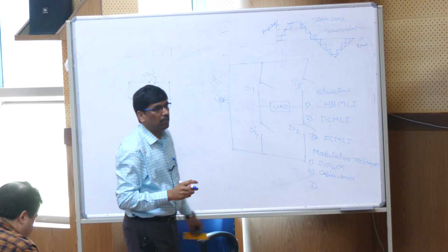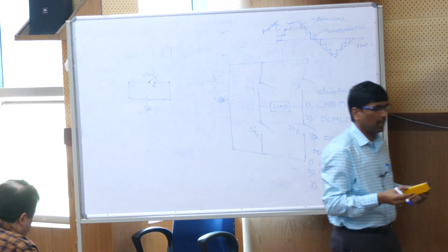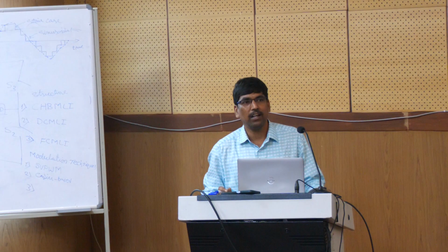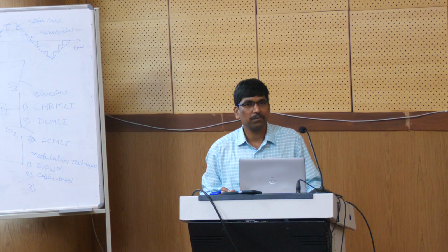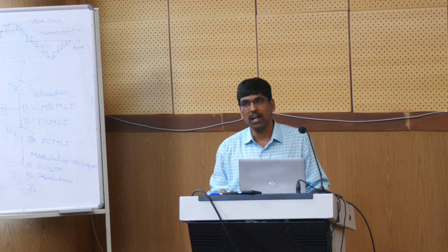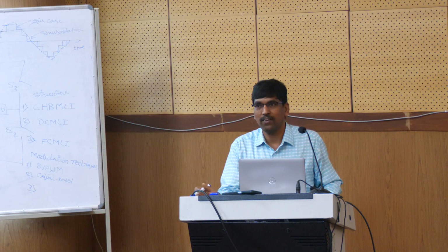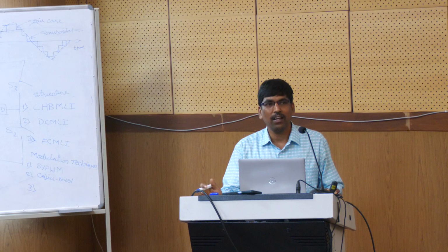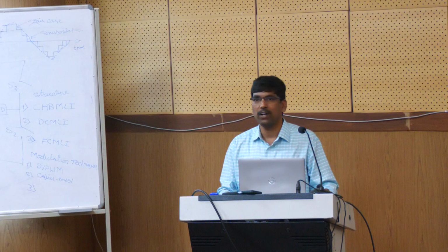When the switch is in on condition, what kind of things will be there? When the switch is in off condition, what are the things? Voltage 0 and the current should be maximum. It should be like a short circuit condition. And when the switch is in off condition, it has to offer the higher voltages and infinite resistance, and the current should be 0. This is the ideal switch functionality.